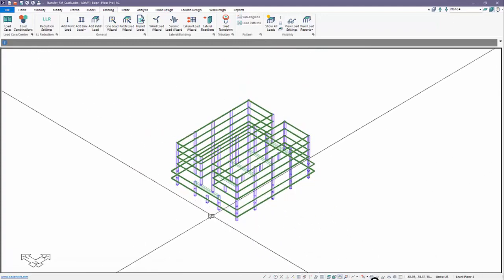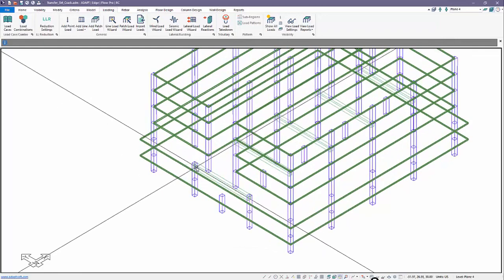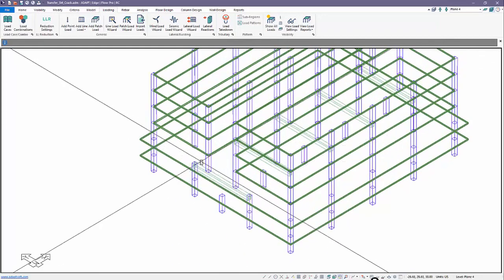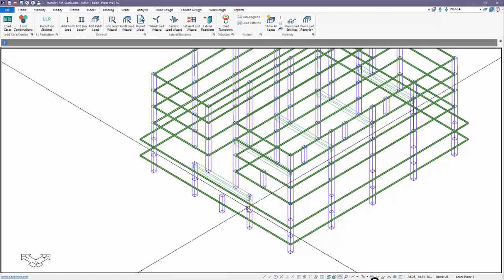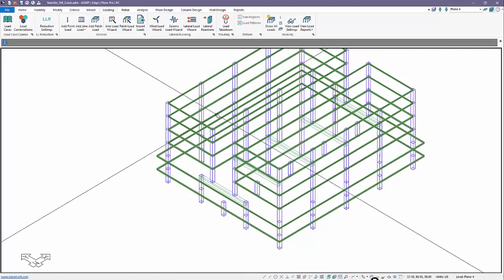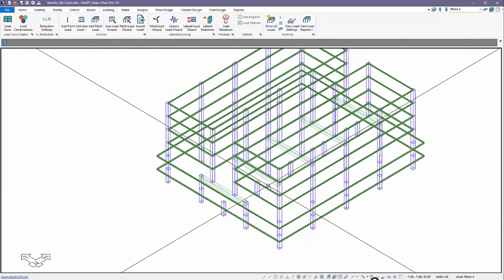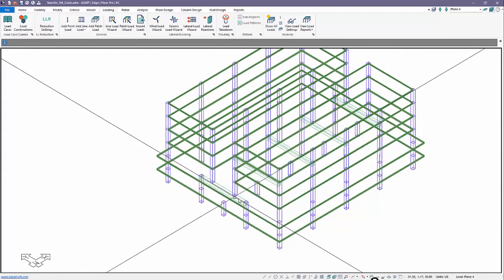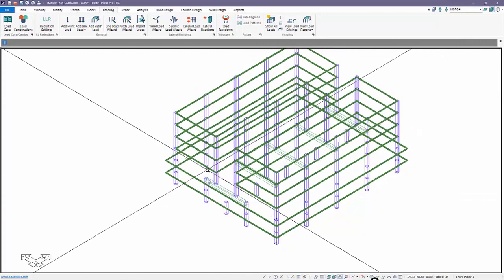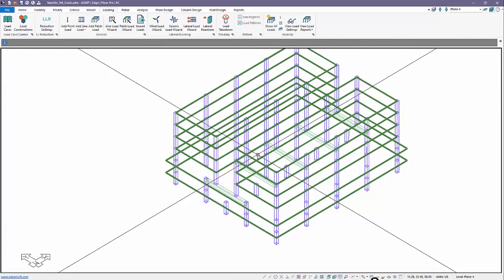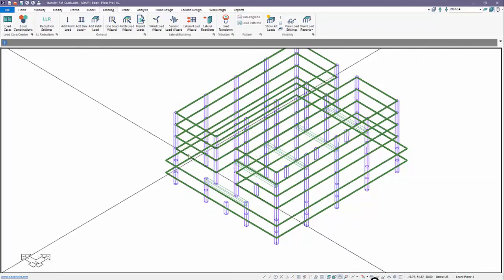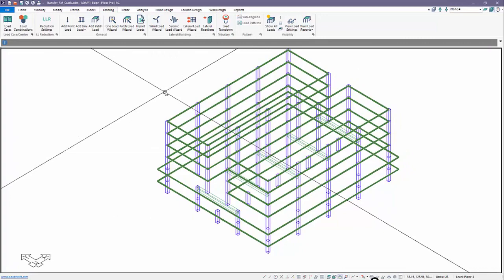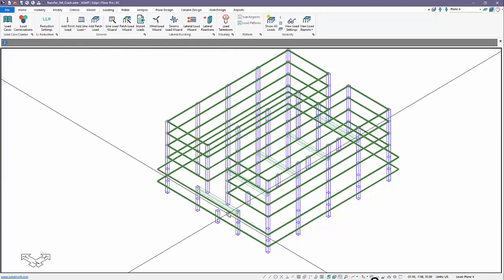Now there's two ways to obtain a design of this beam in terms of the loading. We can use what's called load takedown, and the load takedown means we're just compiling the geometric tributaries of the columns and stacking it on that beam. Or we could run this with finite elements and obtain the reactions and do the same thing. So the first thing we're going to do is run our tributary load takedown. We're going to demonstrate the use of just stiffness modifiers to evaluate the transfer beams first.